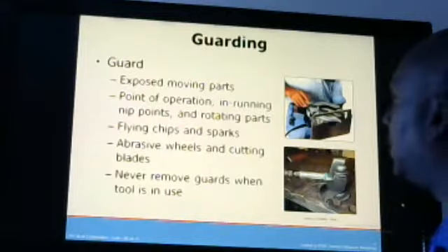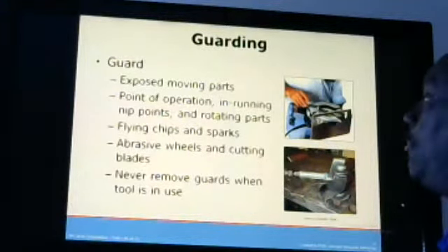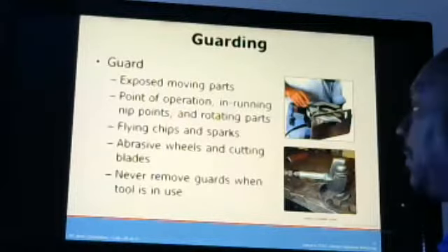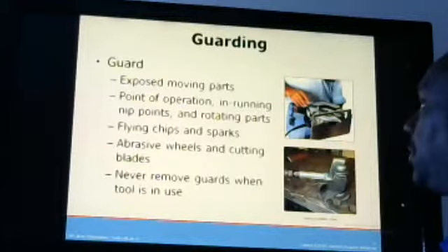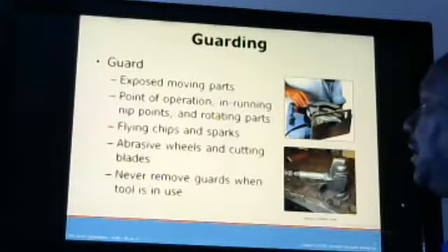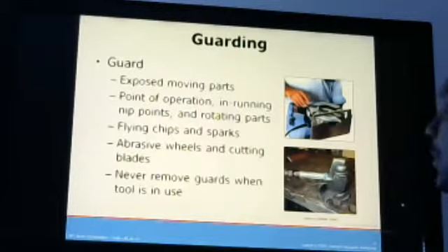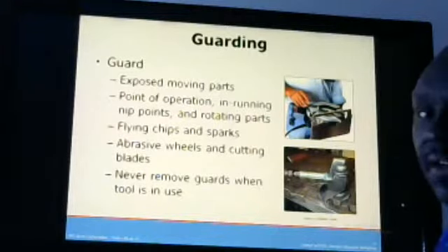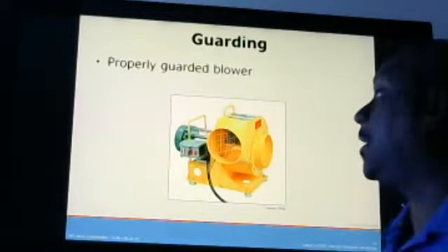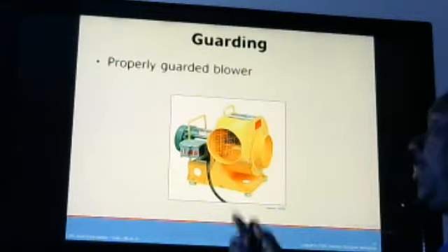So we got the skill saw here. Guards cover exposed moving parts. All moving parts should be covered with some type of guard. Point of operation, running nip points, rotating parts, and flying chips and sparks. Abrasive wheels and cutting blades. And never remove guards when tools are in use. Real simple stuff. And you've got the guard to, again, properly guard the blower. You see it has the proper guard on it.